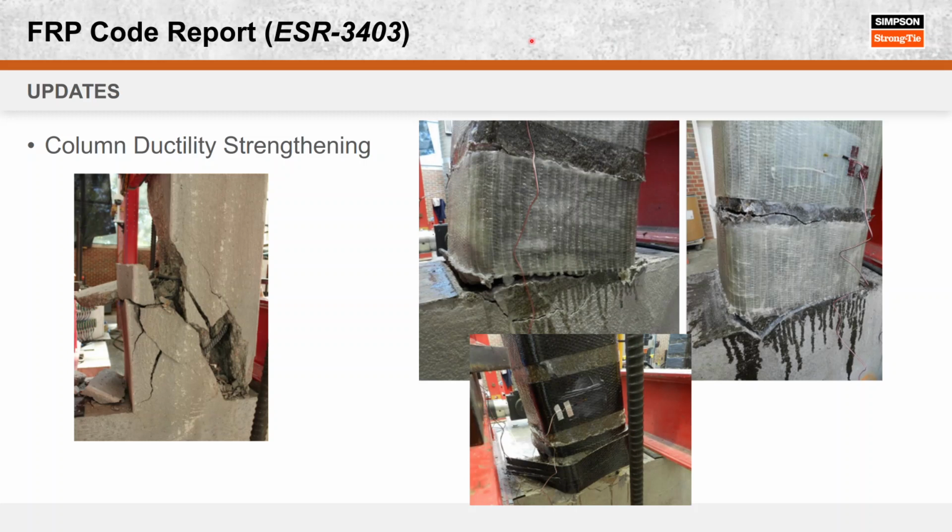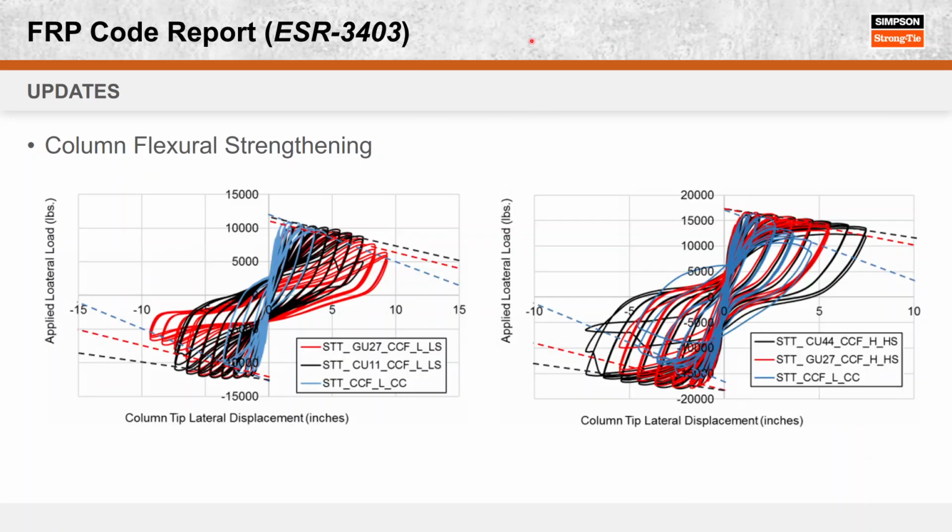Well, they have gaps though. I was going to say confining for a higher f'c, and then you inherently get flexural strength out of that. Basically what we had to show, and I think that's column flexural strengthening, now I'm confusing myself, but we had to show increased levels of ductility. So basically the column has to be able to extend.